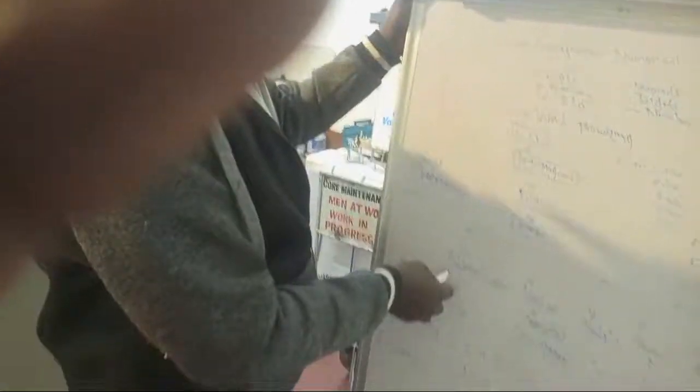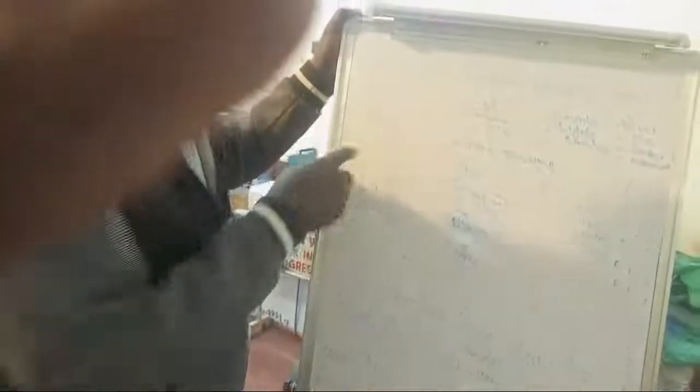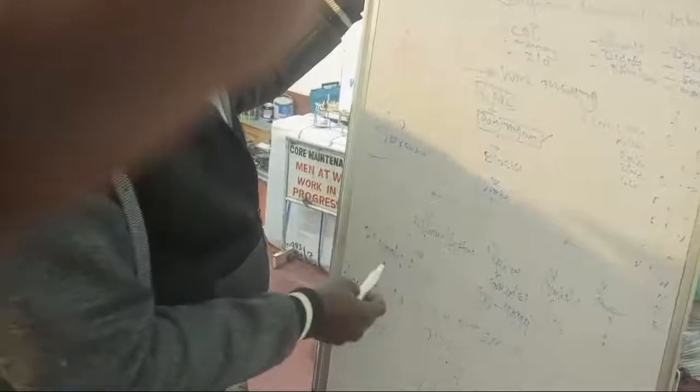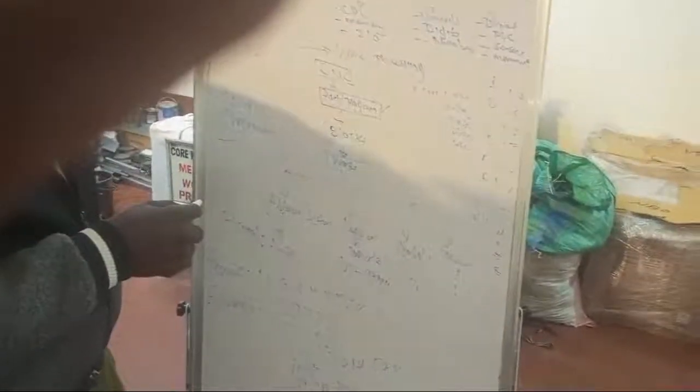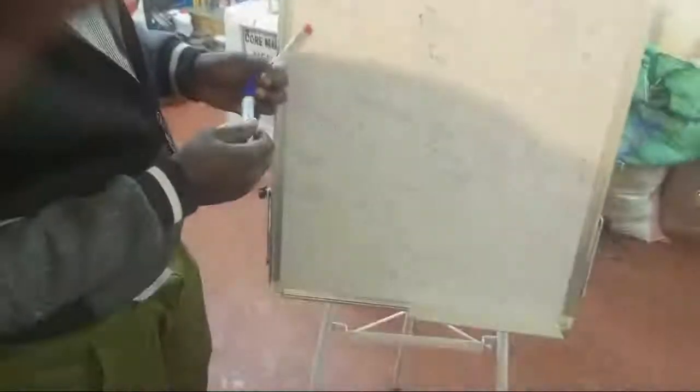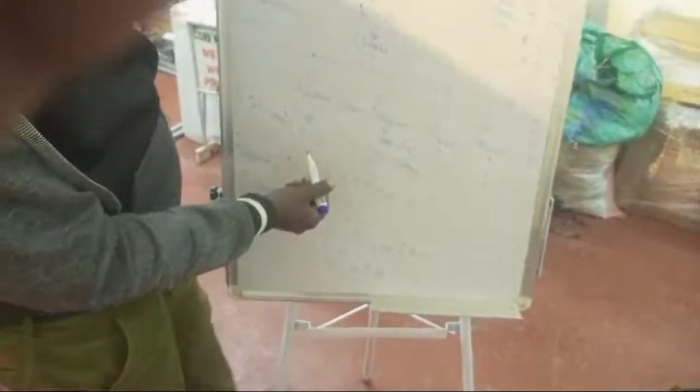In the same way, the machine knows that this address has a specific meaning. When you say G00, it goes to address G and understands the meaning of G00. If you say G01, it goes to address G and has to understand the meaning of G01 so that it actualizes the movement. This is an example of address A up to Z.